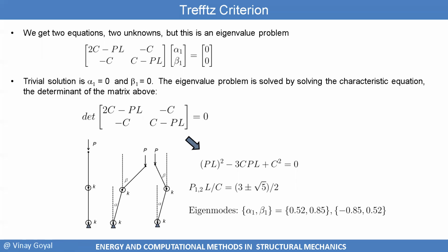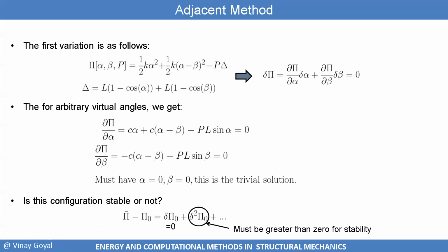And there's an eigenmode that I want you to see if you can figure it out. There's one eigenmode that's more critical. Why don't you pause the video and figure it out and post it in the comment box for extra points. But we're able to find a critical value of buckling using the stress criterion.